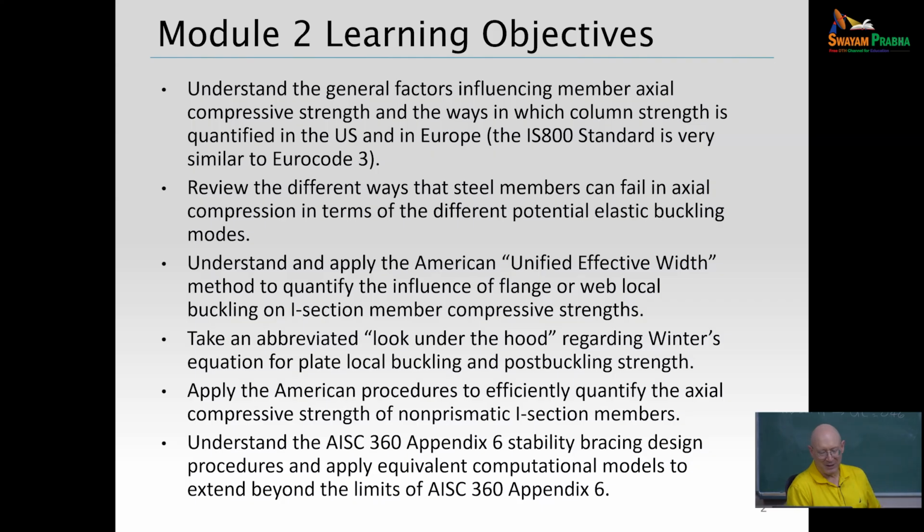And then lastly, I think this didn't show up on the slide that I had posted, but there's some stability bracing design things where the American standards go quite a bit more into stability bracing design, and so I'd like to share some things with you, and how the stability bracing design rules in the AISC actually tie very closely to the direct analysis method, even though they were developed long before the direct analysis method. You say, oh, look, here I do a direct analysis of this, I get those rules. So we'll look at how that goes.